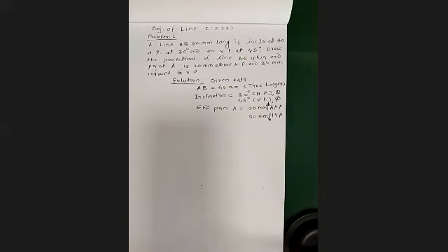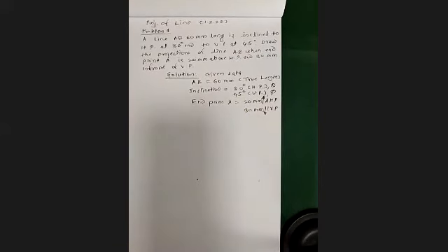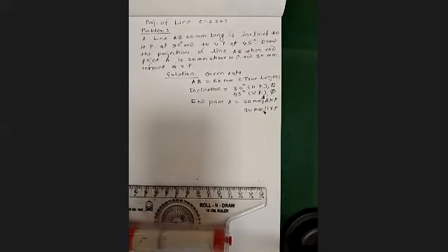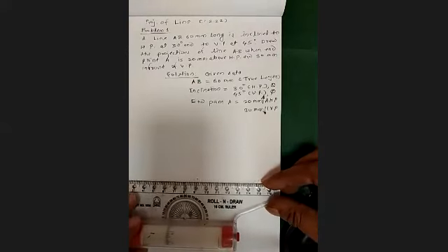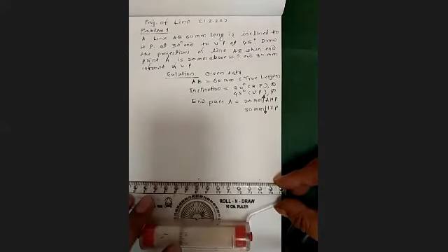Okay. So we'll start with the solution. As we see the few basic cases here, we have to start with the XY line itself. First, you have to get the XY line. And we had discussion that none of the views will be equivalent to true length, means the final front view will not be of true length. It will definitely be less than the true length. So first of all, get the XY line.